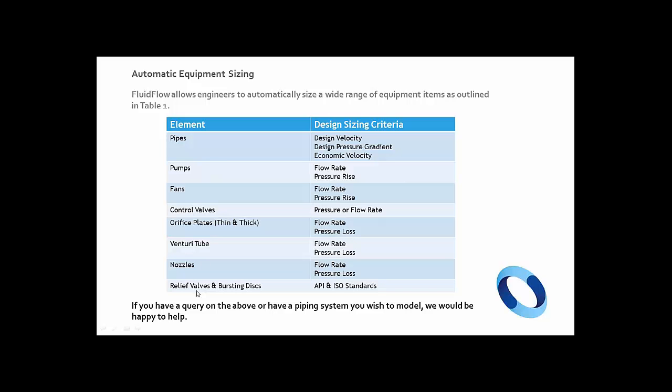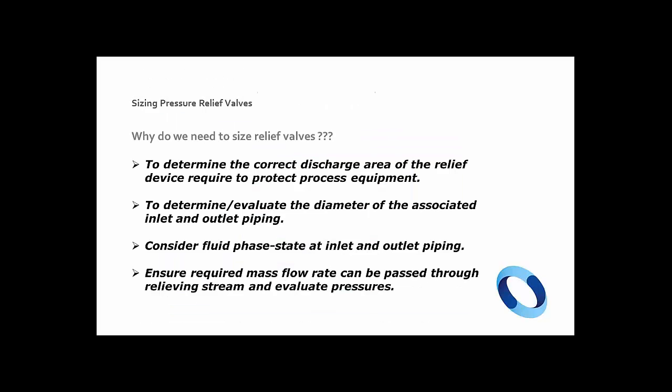And finally, at the end, your relief valves and bursting discs can be sized to API and ISO standards, and you can automatically size these devices for liquids, gas, steam, and two-phase systems. Okay, so that's just a little brief overview of the automatic sizing.